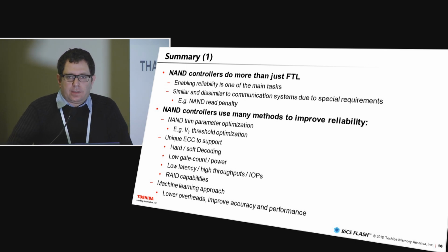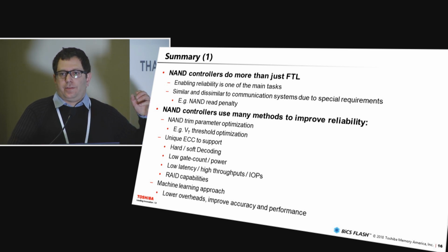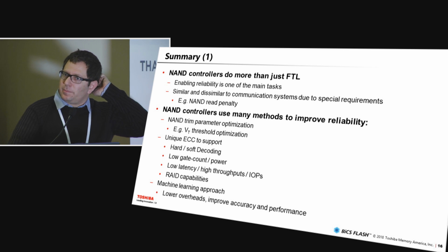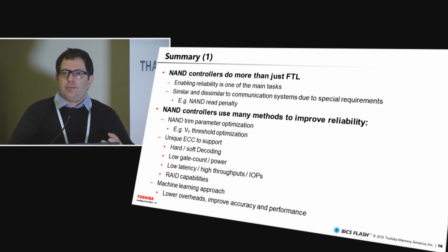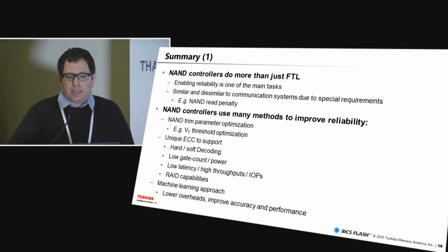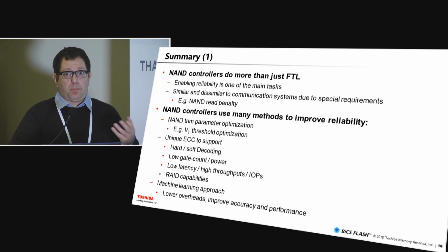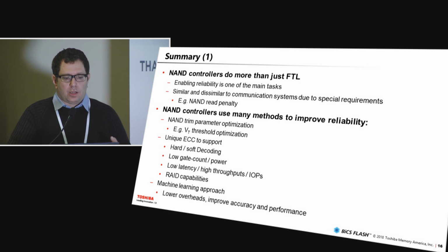So to summarize, NAND controllers do much more than just FTL, flash translation layer. You saw fantastic performance previously, but there's much more going on than just the FTL. You also have much more operation to make sure that the reliability is high. This is both similar and dissimilar to communication systems due to the special requirements that you have from NAND devices, for example, power, gate count, and also the additional cost of having an additional NAND read penalty.